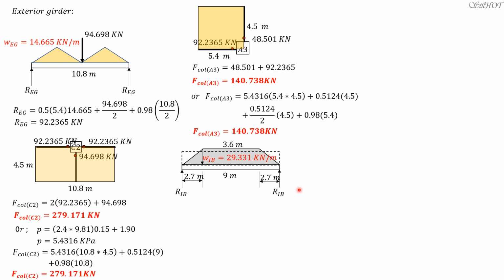So the formula for the long span is PS over 6 times quantity 3 minus quantity S over L closed, squared. Then we will multiply the equivalent uniform load by 2, because for the interior beam, remember that there are two sides, two floor areas, left side and right side. So that's why we multiply the formula by 2.